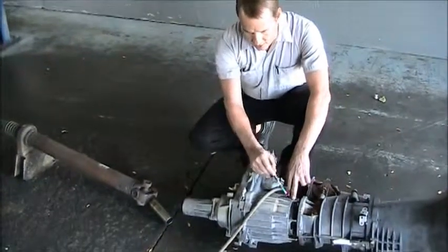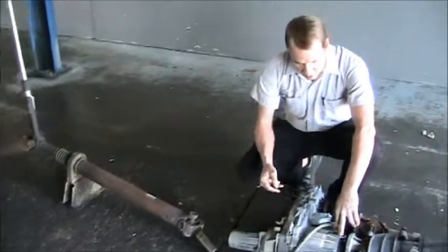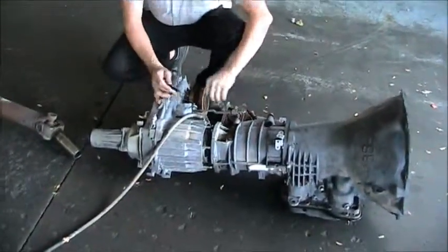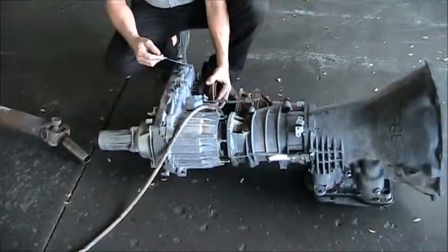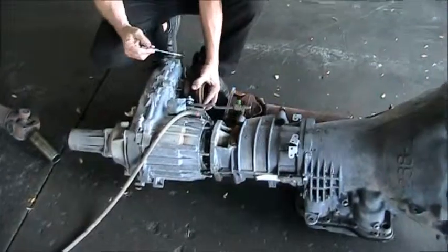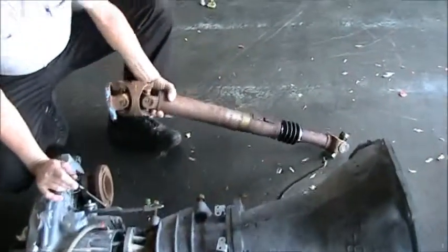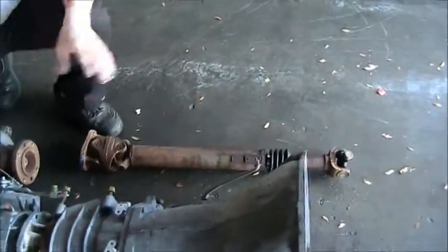It just is a solid shaft from the input to the output, which connects to the drive shaft. Now when you select 4-wheel drive through a separate shifter, it's going to move this lever. It's kind of hard to move, which is going to engage this drive shaft. It's actually engaged right now, which would then connect to this drive shaft here, which is connected to a front differential, and it allows the vehicle to turn all 4 wheels.